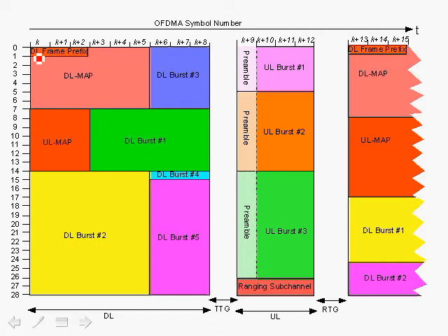Now, there's one particular region which is always fixed in size and constitutes 3 OFDM symbols using subchannel 0 in this case, which is called the downlink frame prefix. And this actually has a number of information elements in there. In particular, it has the frame control header. And this is sent always with QPSK at half rate and in the most robust fashion possible, so that all the subscriber stations can actually decode the downlink frame prefix.